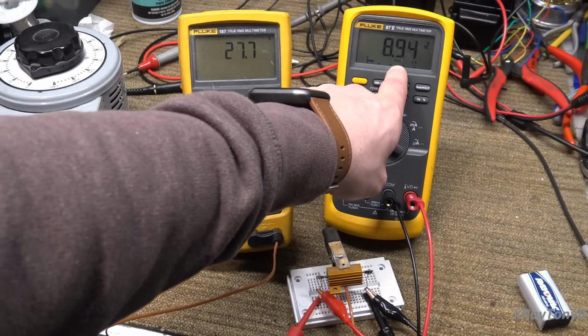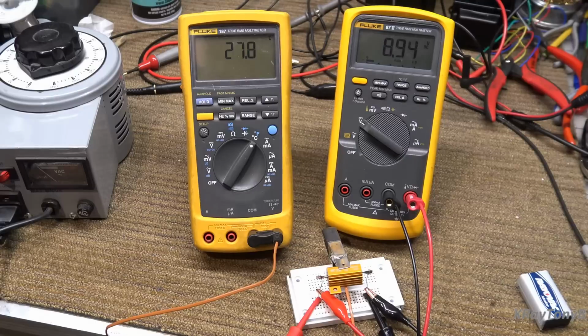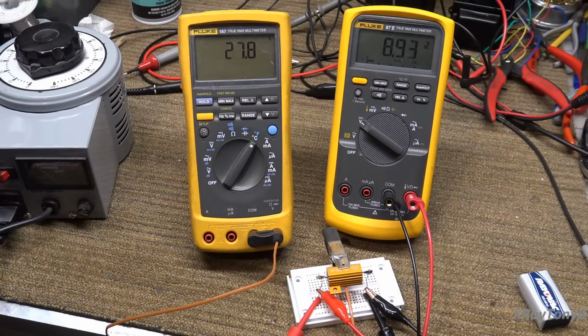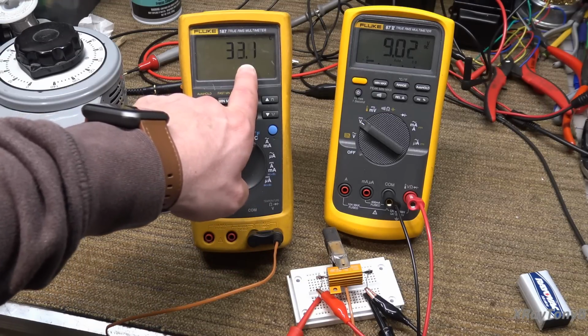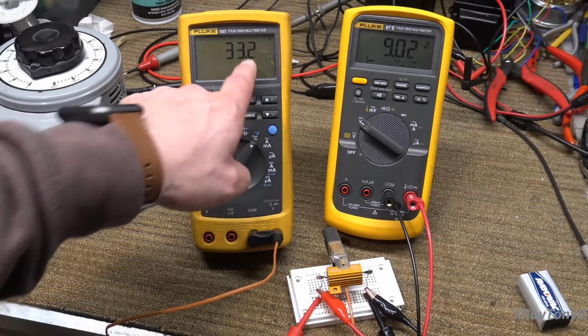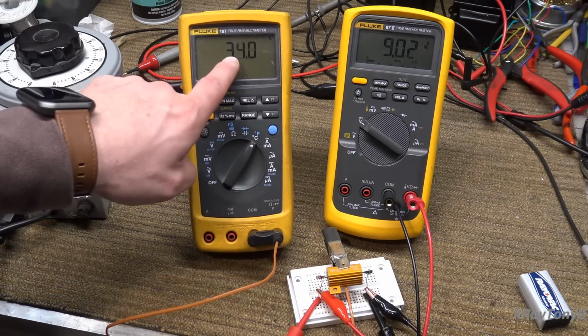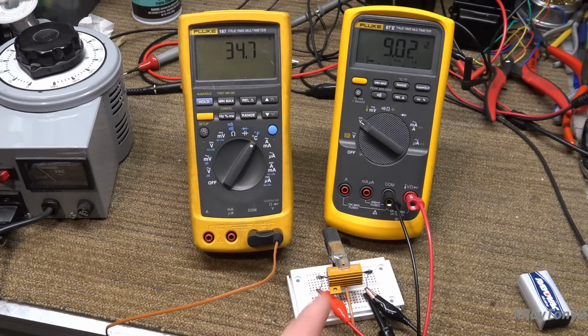And you can see there's approximately 9 volts there, very close to it. 8.94. We can turn it up a wee little bit so we get exactly 9 volts. You can see it's very hard to adjust it perfectly. There we go, 9.01. And you can see the temperature of the resistor is beginning to rise. The reason the temperature is going up is because that energy is being converted into heat.